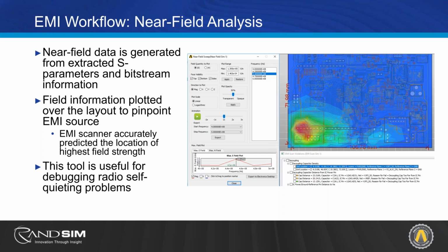With Gerbers, the challenge is that you don't get the net linkages very well because it's coming in as layers, and the ODB++ will typically import much more nicely. And fortunately, if you have any of the main ECAD out there, Mentor Graphics, Altium, there are Ansys videos online that walk you through all the steps on how to generate the ODB++ files, as well as the component files, so that when you import it in, it all just comes in and is ready to go.